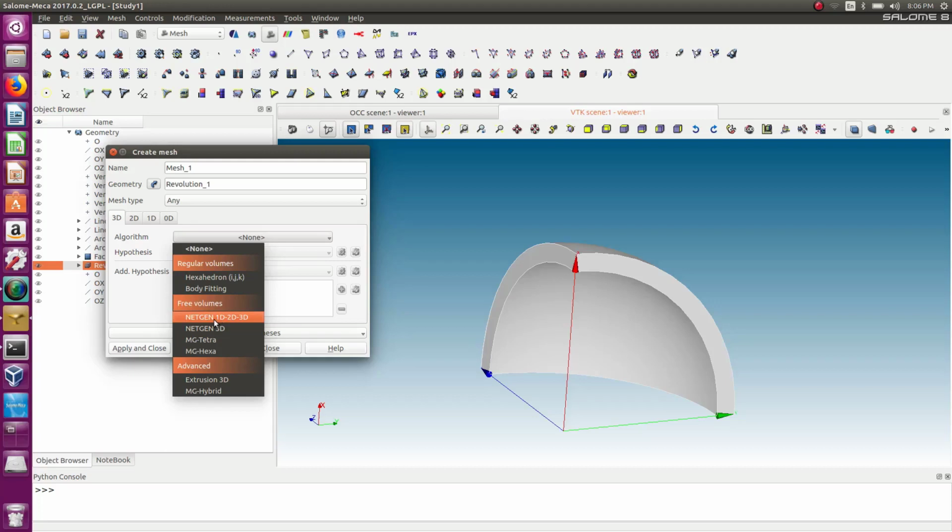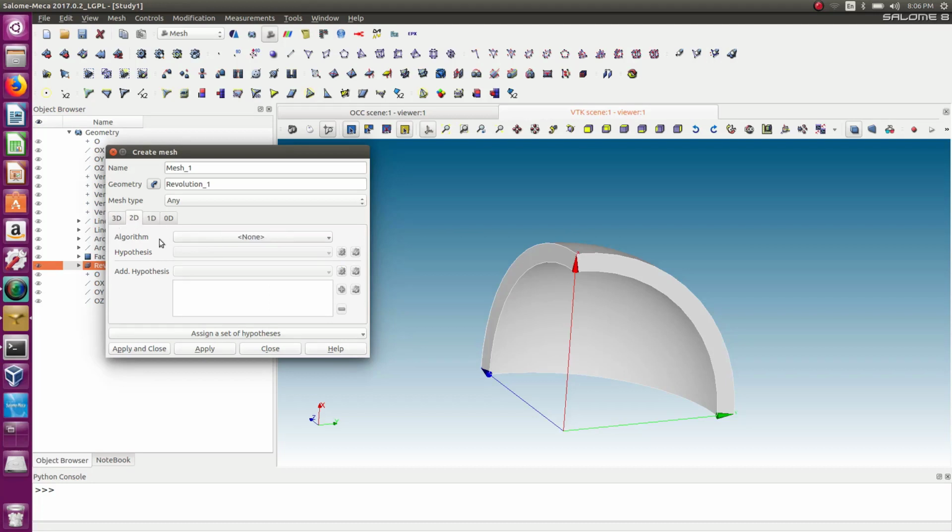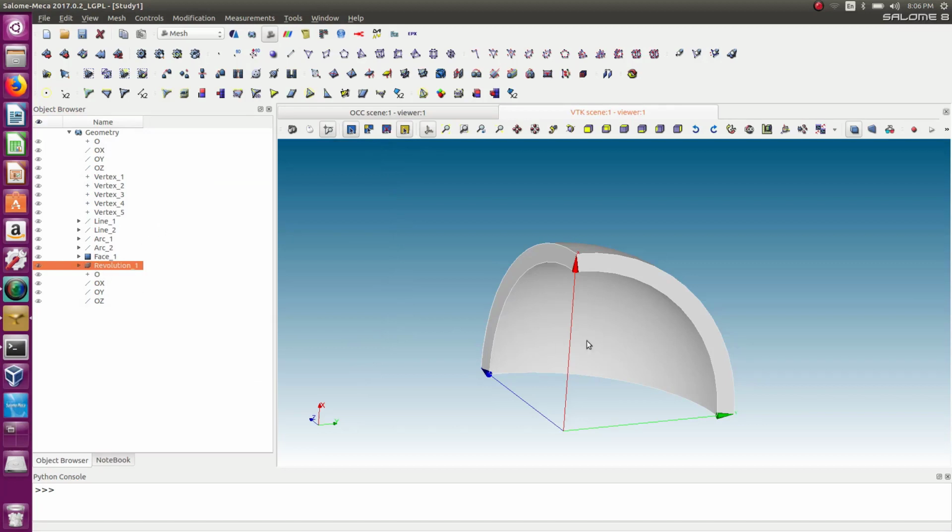So how do you do that? Well, if you use this hexahedron, then it becomes a bit difficult to define the other types. Basically it's not working exactly like I want. So what I found as the solution is to mesh only this surface, and then to revolve it around this axis manually to create the mesh. So let's do that.